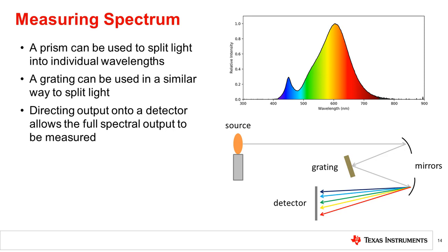While spectrometers offer the best performance in terms of light sensing, this performance typically costs several $1,000s, and spectrometers are bulky in size. Additionally, the grating is sensitive to the angle of incoming light. In typical indoor and outdoor settings, light comes from many angles, meaning that spectrometers are mostly used in controlled laboratory environments where the light entry can be controlled. We will now discuss sensors that bring cost-effective light sensing capabilities to everyday devices like phones, cars, and thermostats.